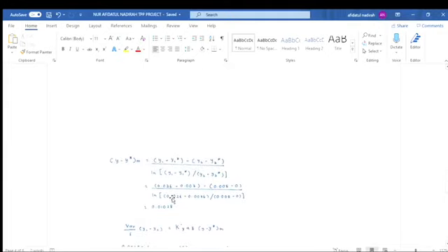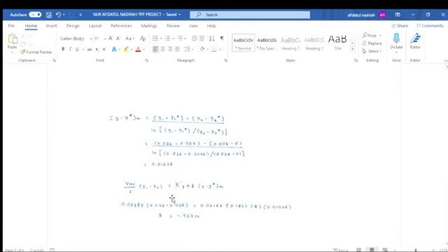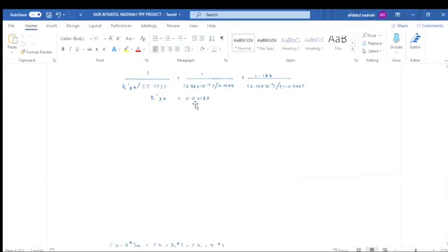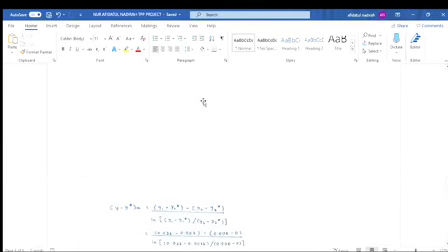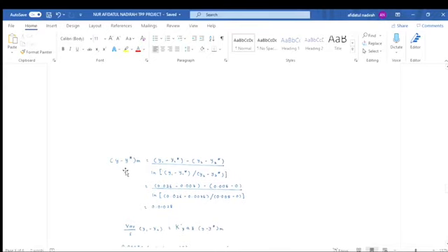So, K capital YA we already got. In order to find the value of z, this is the equation: V average times (y1 minus y2) is equal to K prime YA times z times (y minus y star m). So we have to calculate y minus y star m first.